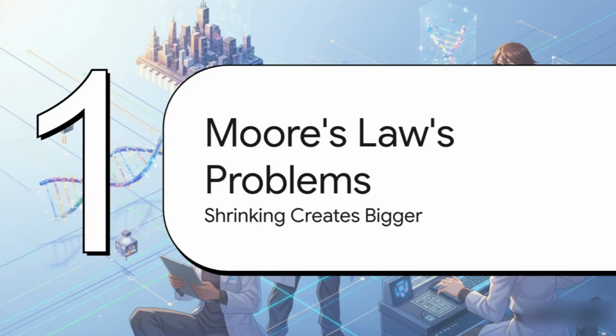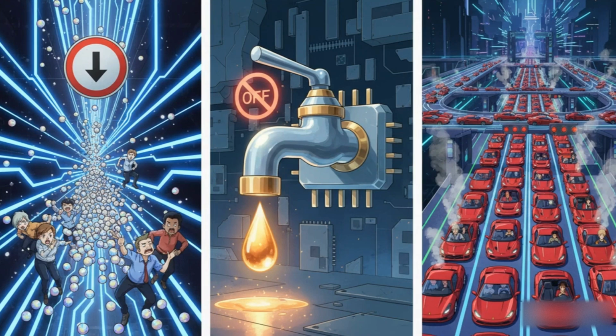As we push deeper and deeper into what we call deep submicron design, just making a transistor smaller, it's not a simple win anymore. It actually creates this cascade of new and frankly much bigger challenges. It's like you solve one problem, but you accidentally create three more. And this really shows the three main hurdles we're up against. First, you've got velocity saturation. The electric fields inside these tiny little transistors are so intense that the electrons basically hit a speed limit. It's like a highway where it doesn't matter how hard you stomp on the gas, the car's just not going any faster.